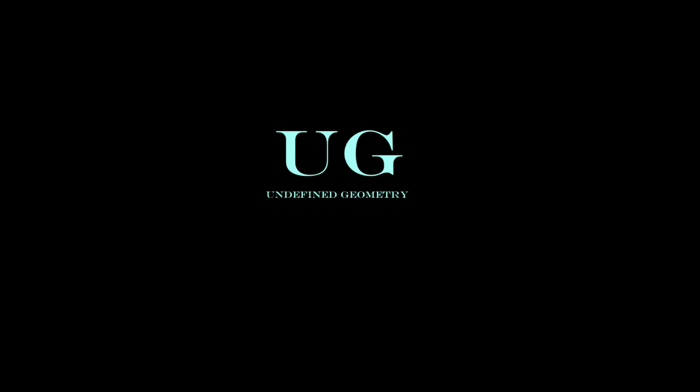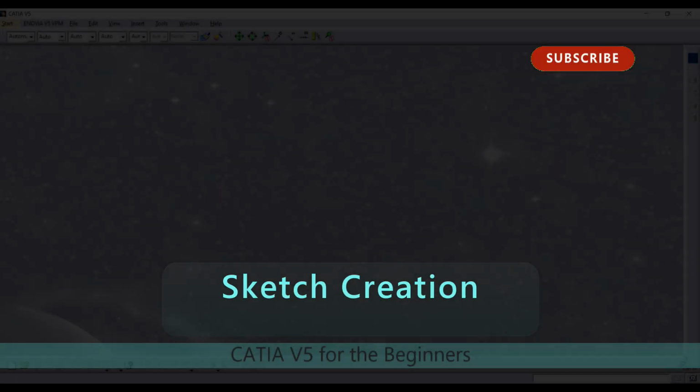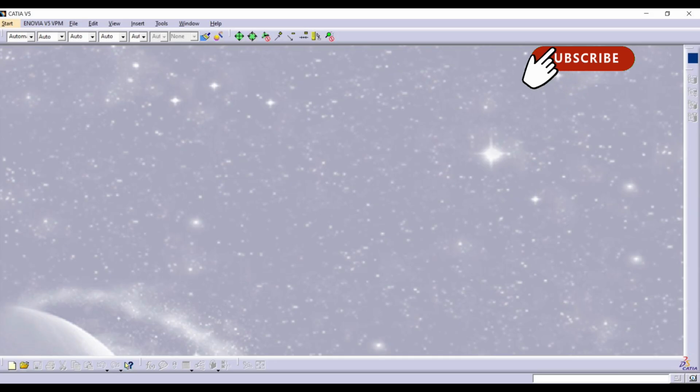Welcome to Undefined Geometry. Today we are continuing our beginner's lesson with a look at the sketcher. A sketch is the starting point for most 3D models. The primary use for sketcher is for the user to define precise and rapid 2D profiles. These can then be used in the definition of surfaces and solids. The sketch has to be defined on a 2D plane. This makes the profiles quick to produce, very accurate, and can be easily changed.